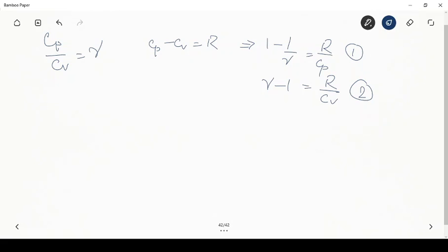So now these two expressions can be useful in deriving the expressions for the other quantities. So du and dH can then directly be evaluated using the specific heats that we have defined now, and they are only functions of temperature, so if the specific heats are known, then we should be able to define all the other quantities in terms of those. So that is the way ideal gas properties are evaluated. Now ds, the change in entropy; internal energy and enthalpy are done.